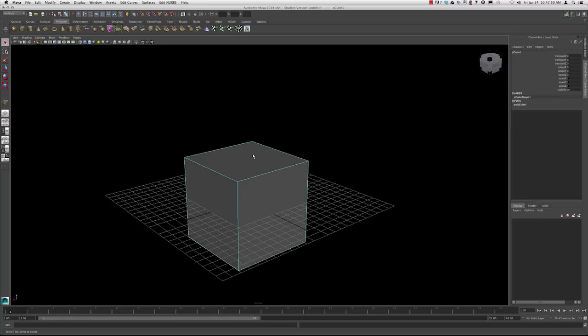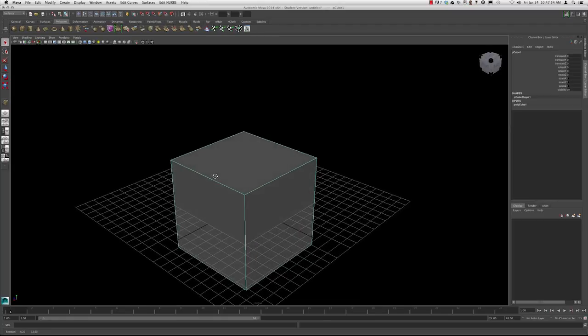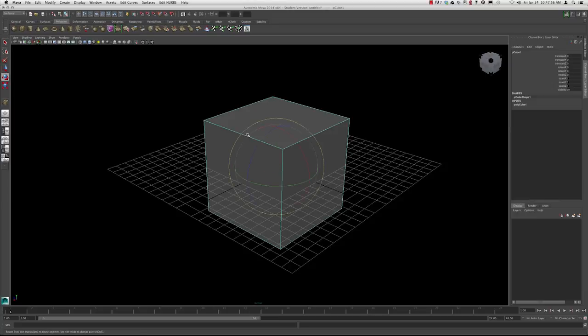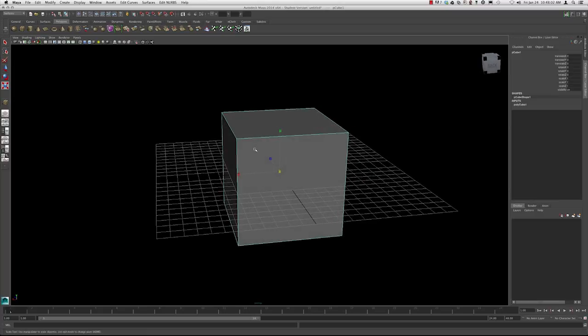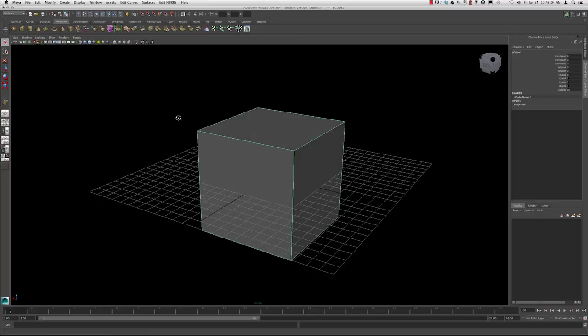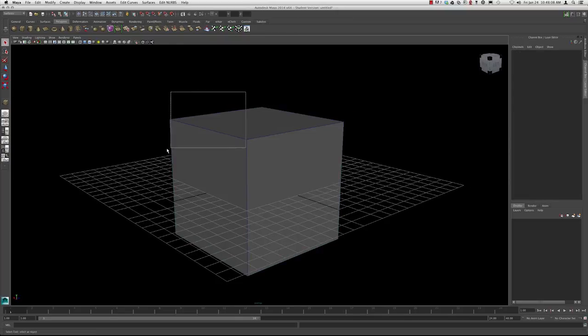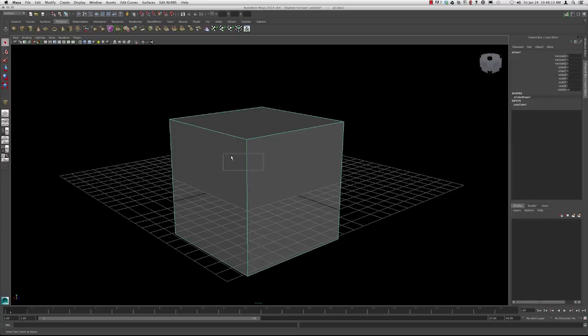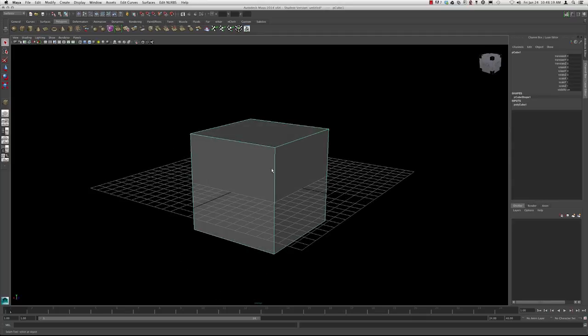And that's because the select tool is what's set right now, not the move tool. And so I'm going to talk about the 3 hotkeys that are going to make your life incredibly easy. And that's the W, the E, and the R. And you can see that the manipulator changes every time you do that. By default, you probably had it set to Q, and Q is the selection tool. The selection tool allows you to select any objects or any geometry without accidentally moving it.